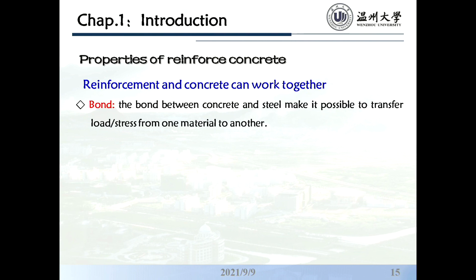This is a reinforced concrete with steel bars. In summer, the concrete has a bigger value, it expands, and the steel bars also expand. If they had different coefficients of expansion, in summer the concrete would expand this much, but the steel bars would only expand this much. So there would be a gap, and there would be high stress. That is not good for the structure, not good for the structural member.